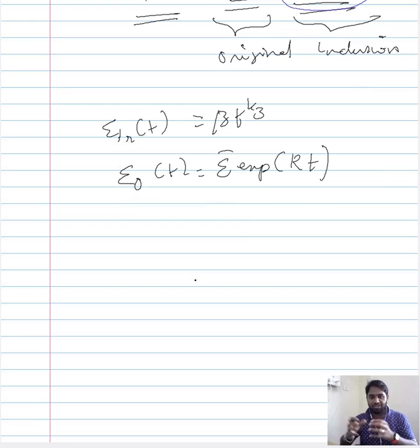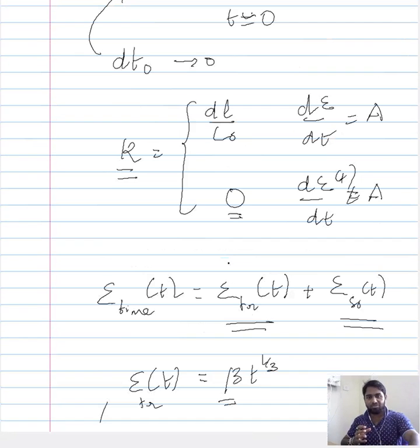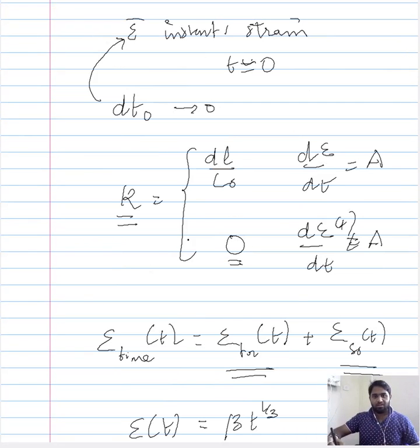Now, the final stage of the time development period is the steady state stage. So, this represents the final stage of the time development period. In this stage, what you have is a more or less constant slope, or more or less the same creep rate. So, that means if you go back to this description here, this is nothing but the change in strain, or the change in the length of the material, for a definite period when the slope is constant, or when the strain rate is constant.